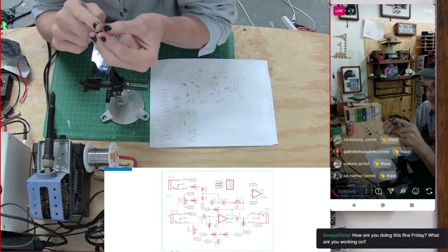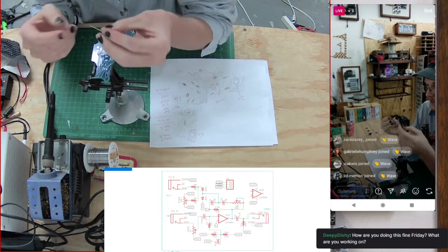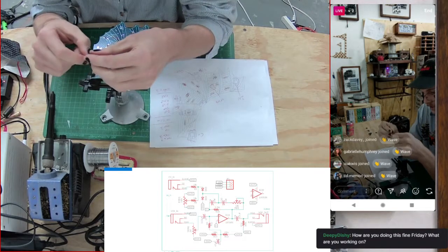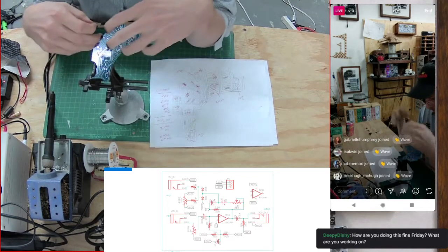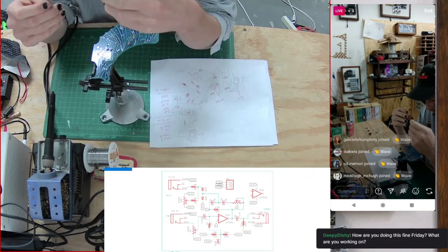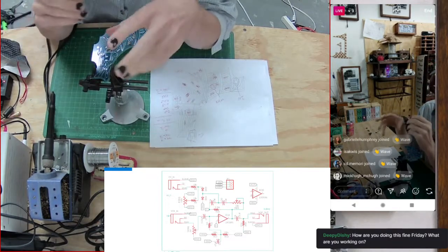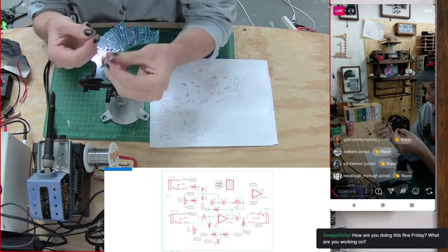They have to be connected that way, otherwise they won't work, or they might pop and get burned out. The ceramic ones aren't, and the resistors are not polarized. They can be put in either way, back or forth. These ones you have to put in the right way.